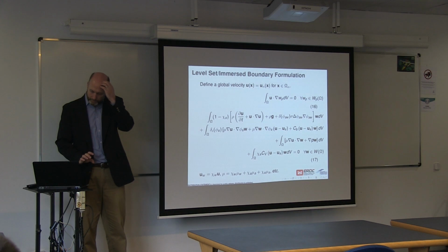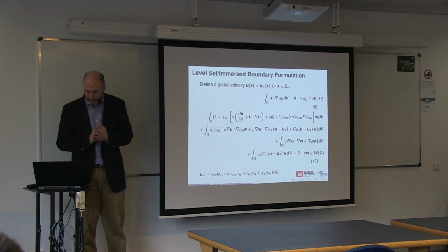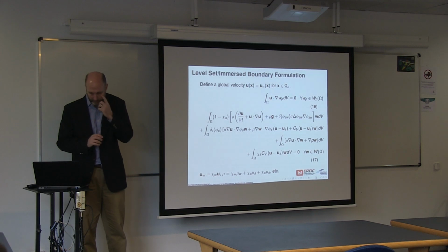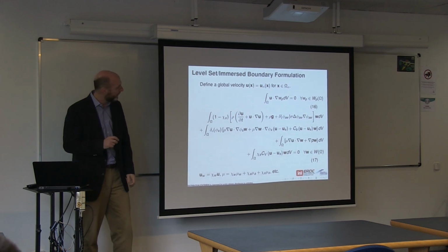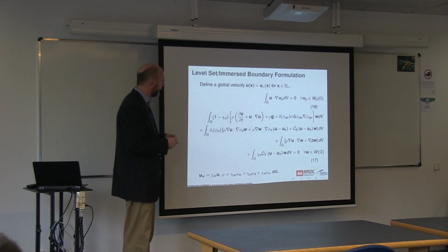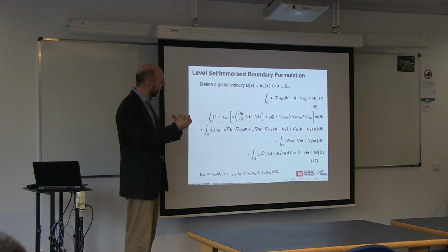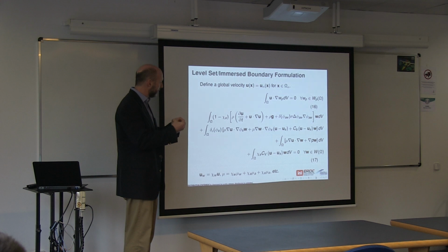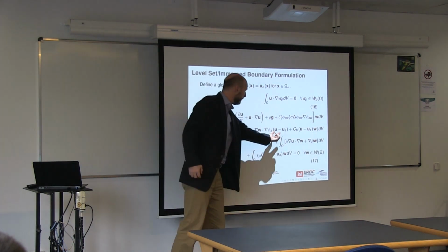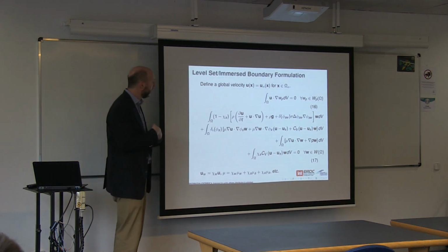So this is really the heart of one point of my talk that I came here in part to discuss with Santiago. We've been using an immersed boundary method to enforce the no-slip condition at the solid grain. So at the surface of each grain, we assume continuity of the velocities. And so we need to actually enforce a no-slip condition, which is really that u equals u_s at the boundary between the fluid and the solid.